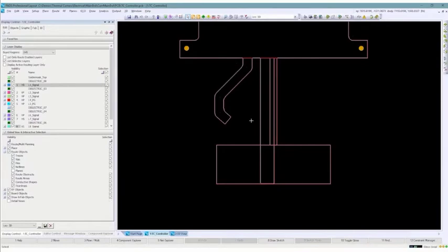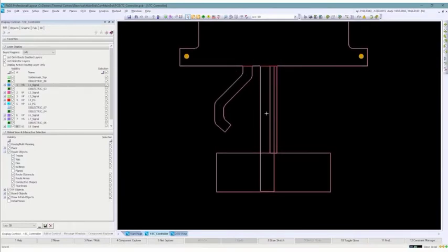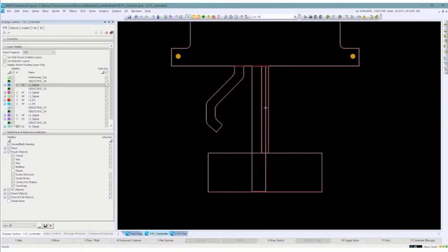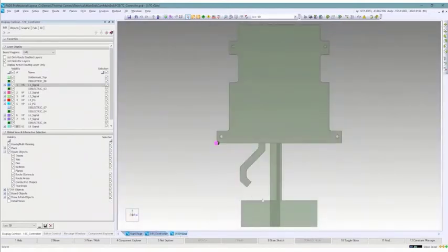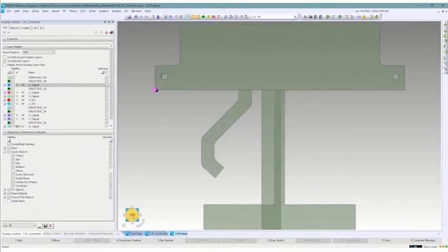So this is, again, where the important part comes in. Some CAD tools out there, when you have overlapping flexes like this, you have to define a stack up by each individual little shape. So if I adjust this shape at all, I have to go in and readjust the regions for those shapes, or what stack up is going to be assigned to that. With PADS Professional, it's all just based on a board outline. It doesn't matter if I adjust this board outline or not, it's always going to use that same stack up. So it simplifies your entire process of creating a rigid flex board. All right. So now if we go into 3D real quick, we can see all of these different regions now.